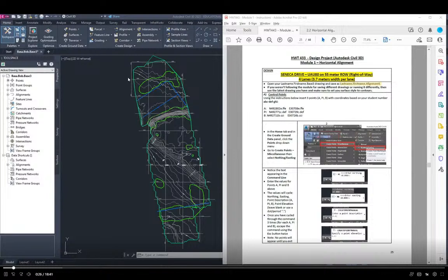In this video, we're actually going to create the road alignment on our ground. We're going to place an A point near the north end, a B point near the south end, and then a point of intersection, our PI, is going to be here in the middle towards the east side of our ground. Then we're going to create our road, which is going to have a tangent with a spiral curve spiral system in there.